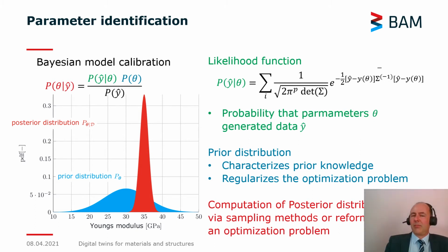Based on that, you describe by a likelihood function how accurately you can measure the compressive strength or whatever parameter you're interested in. Then you put that into a Bayesian inference procedure, and you get what we call a posterior. That's augmenting the prior distribution by data to get more information.